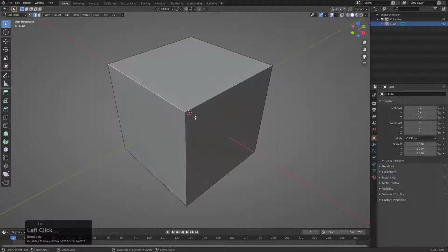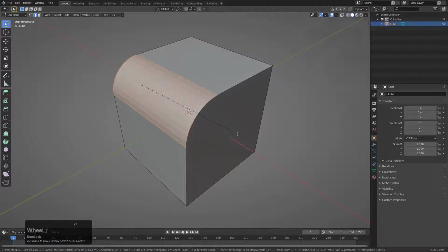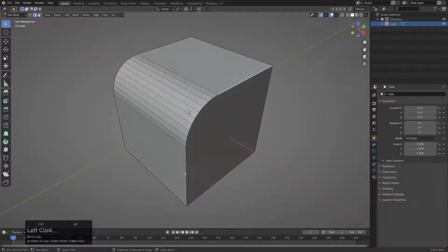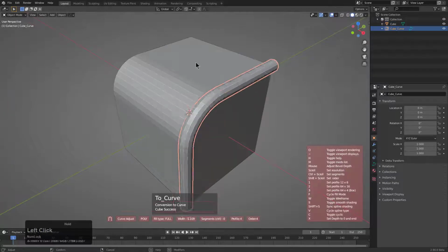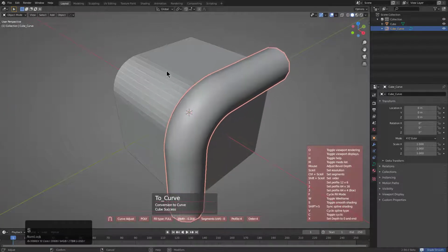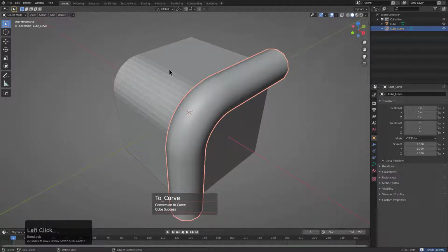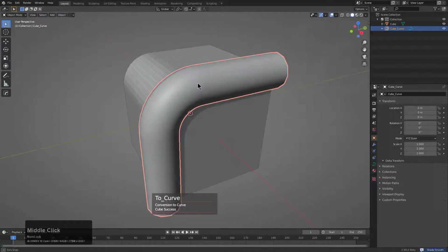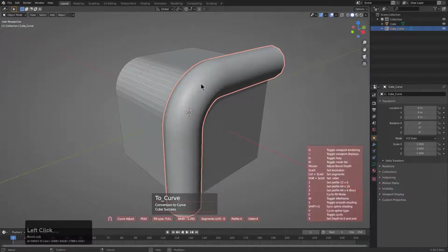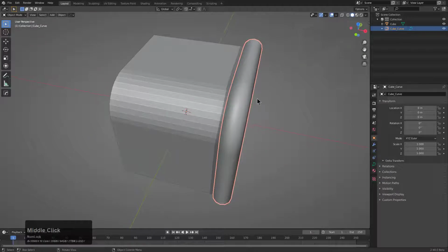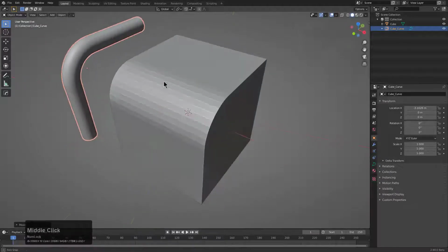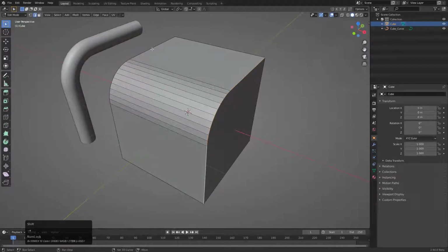curve. And my favorite case to demonstrate it and test it is to basically grab an edge and bevel it manually, and then just click one edge and control click the other edge to set up my selection, and then just click it to convert it to a curve. So now that it's a curve, I'm able to go in object mode and adjust the curve just using the Q menu. There's always a Q menu, that's like a meme as well. There's like a Q menu for that.